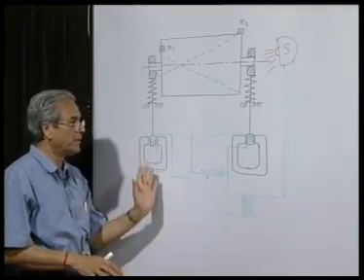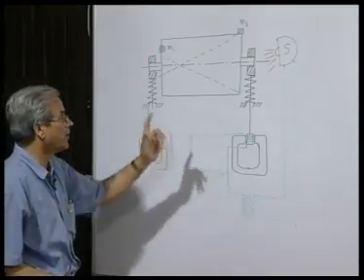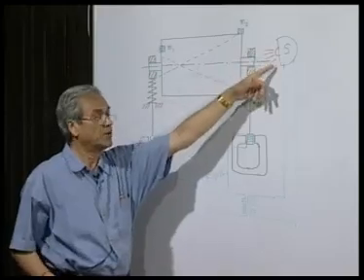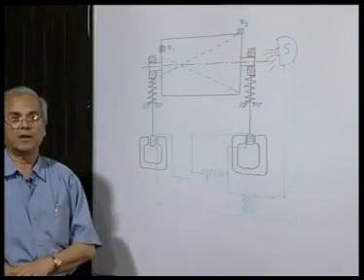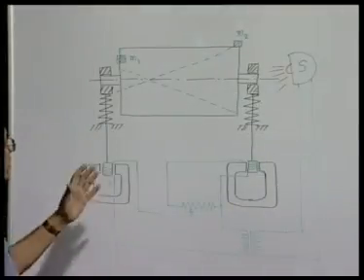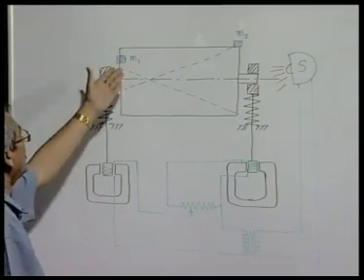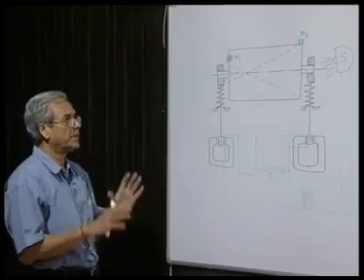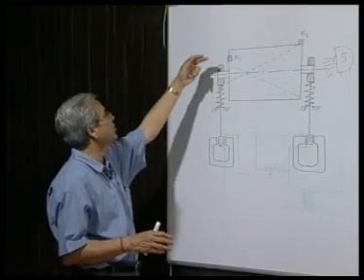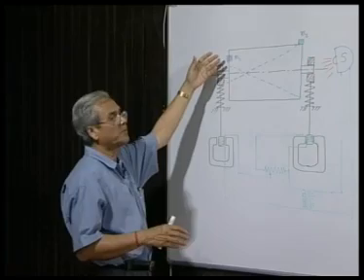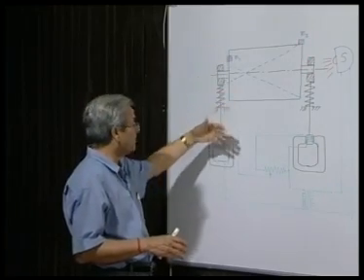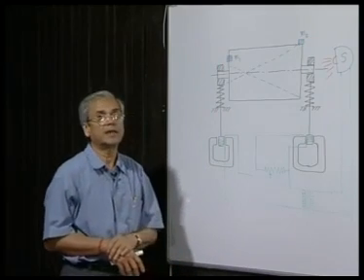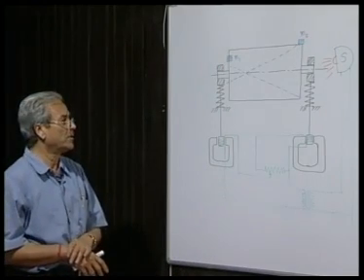So, depending on which circuit we are using, we can find out the angular position of this and of this using the stroboscope. This can also tell us the magnitude of the two unbalances present by suitable calibration. The basic principle is that you slowly adjust the magnitude of the product of the mass and its eccentricity in such a way that the result is minimized to 0.